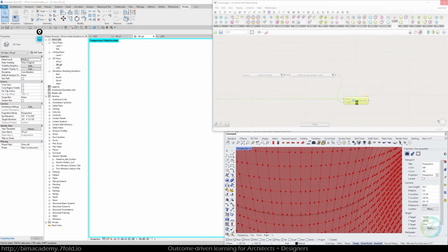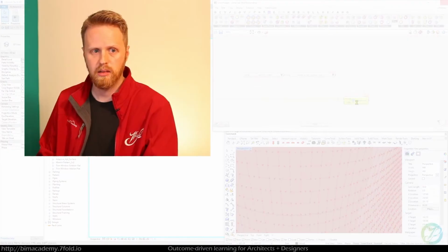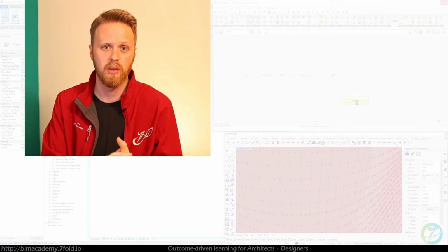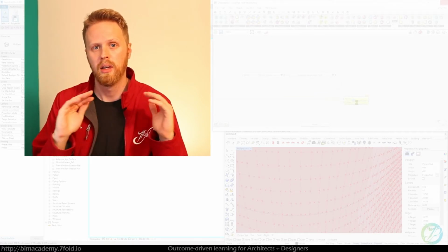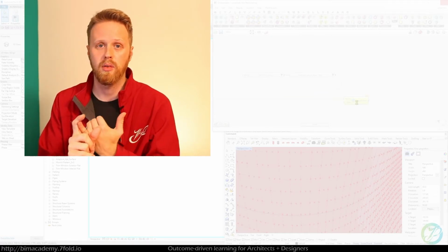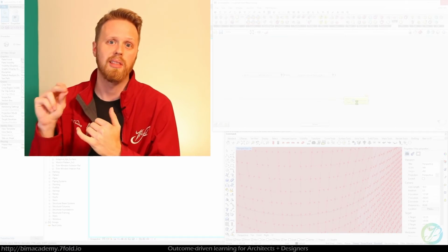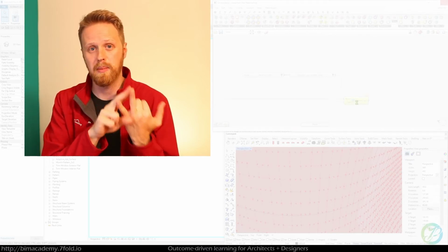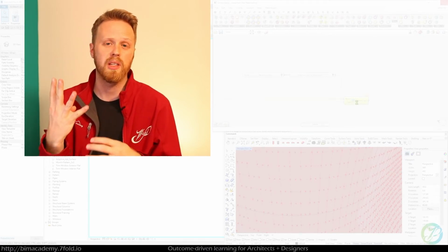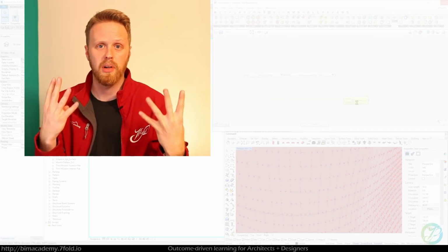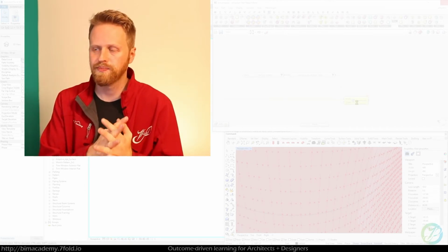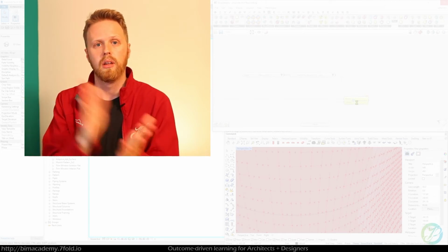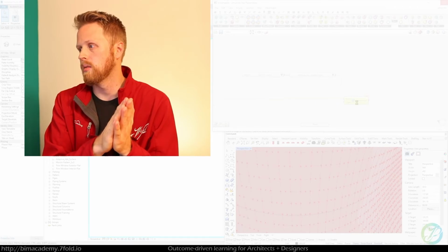Make sure you're double checking your data before you put it into this component. It's super critical. You could crash Revit, you could crash Rhino. Just double check your trees, your branches are lined up. You've got the right amount of points to match up with the adaptive points, right? So if I had a 4-point adaptive component, I've got 4 points in each branch, and those all line up as intended. And then go ahead and run it. So I'm gonna go ahead and cut to the end, and we'll keep going from there.